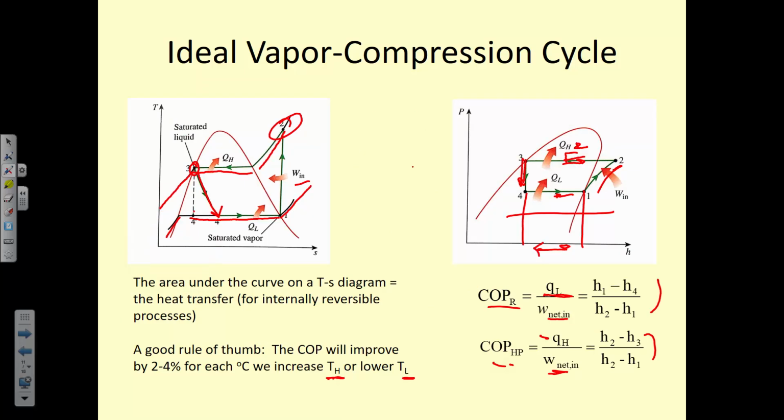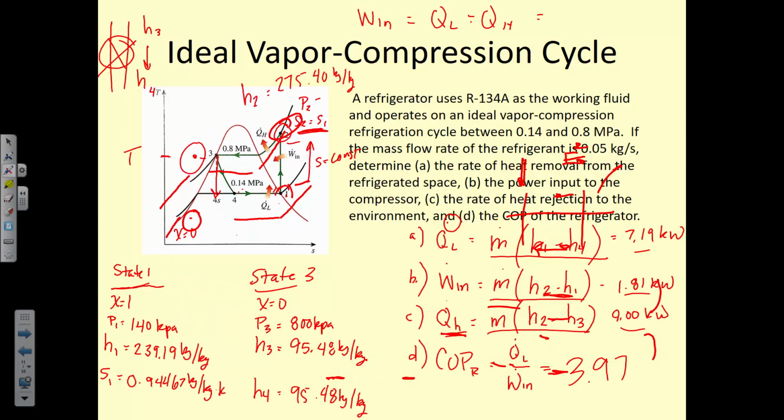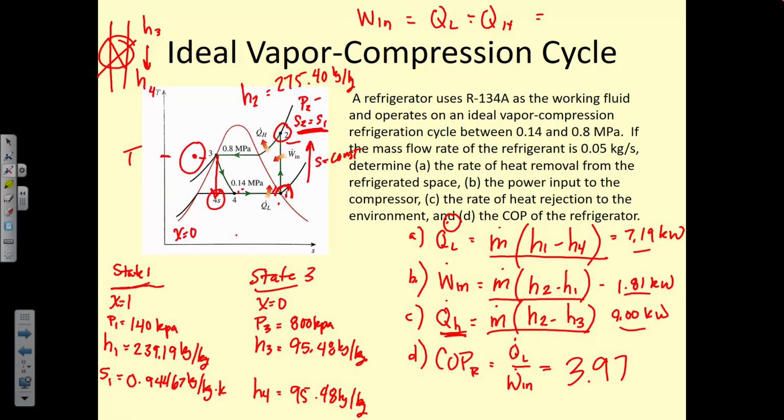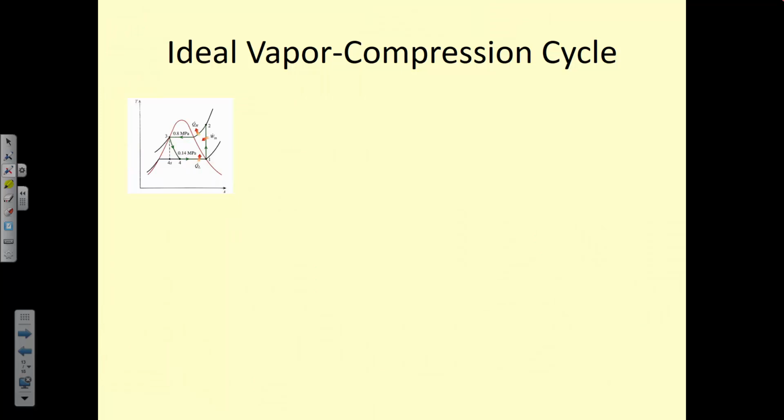So that would also give us a network out if we used a turbine. Oh, interesting. We could apply that back to the compressor. Right, so we're going to have some network out that we can potentially use to power our compressor, or part of our compressor. Probably it's not going to be enough to power the whole compressor. So we need to find our new state 4. Instead of going here, we're going here, this 4 prime on the picture, this 4S here. So let's replace the throttling valve with the turbine, and we'll do the new analysis.